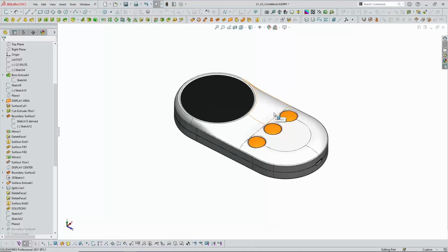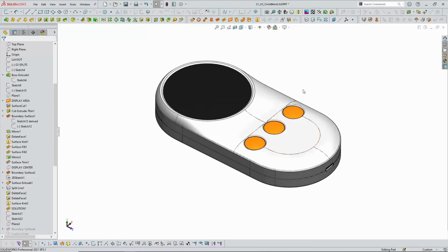and ultimately I was able to create this very smooth flowing geometry where I have very simple shapes, but the geometry between those simple shapes isn't so simple. And with the fillet tool, I wouldn't have been able to get to a solution, but using some of the techniques of manually sketching splines, creating surfaces, and then blending between them gets the final geometry that I was looking for.